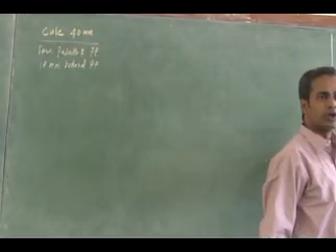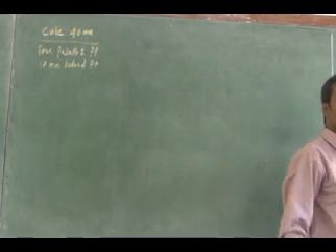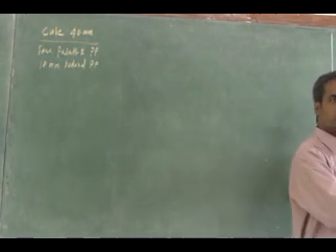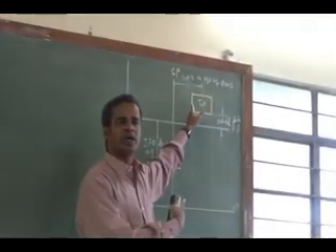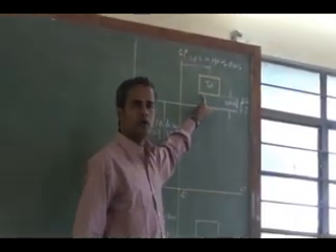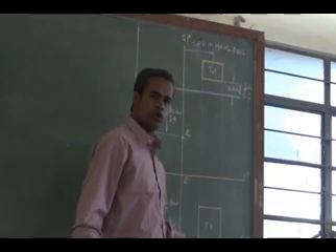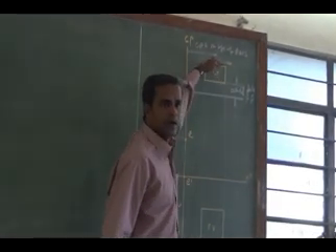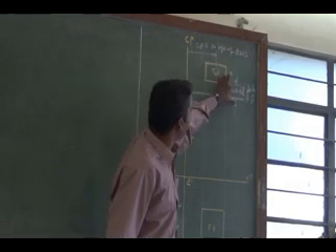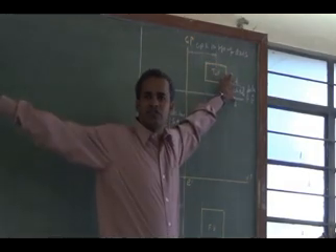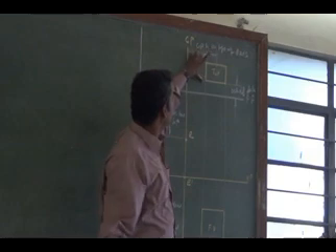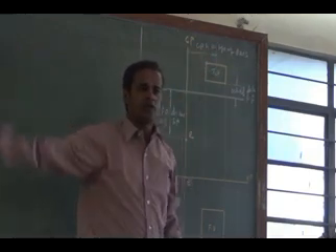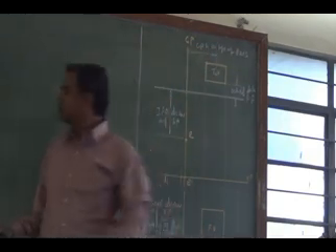You see here, the cube's top view and front view are both going to be the same. What is the top view of the cube? Square. Front view of the cube? Square. So one face is parallel. The cube I have to draw. One face is parallel and this distance is given. What is that? 10 mm. And the size of the square is given, that is 40. Right. So this is the first detail.